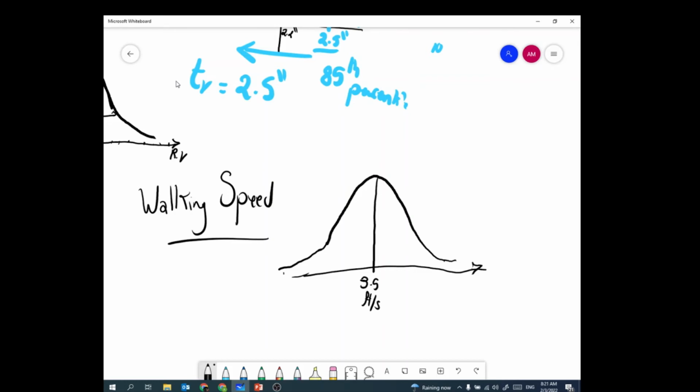When I want to find a number to design, for example, a push signal, to figure out the speed of people crossing the road so you can give them enough time to cross in the signal, we want a number slow enough to capture 85% of the people. And 85% is a statistical value that tries as much as it can to capture. Again, I cannot capture everyone. I cannot say my speed is 1 foot per second. That's turtle speed. So again, I cannot design it that way. It's going to drive my system crazy.